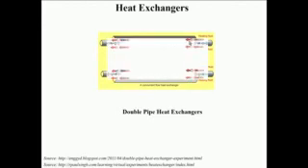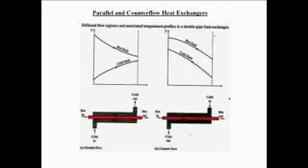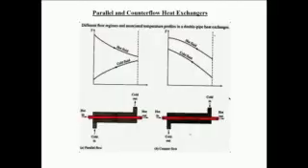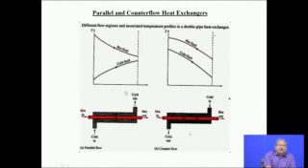So you have a flow taking place through a double pipe, and through the annular another fluid is moving, and therefore you get a very good heat transfer in such a case. This is interesting conceptually. If you look at the figure carefully, the direction of flow of the cold fluid and the hot fluid is the same. The two arrows denote the direction of flow of the two fluids, and the hot fluid temperature is going to come down. This is the exit temperature of the hot fluid.